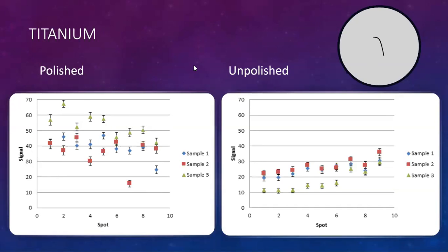On the polished side, we saw the signal decrease, and on the unpolished side, we saw the signal increase. This makes sense because they're experiencing opposite types of stress, so on one side we see it decrease and on the other side it increases. Essentially it tells us that the further away from the damage, the more it seems like an undamaged sample. So you could potentially use on-surface referencing to know if your damage is significant or not.